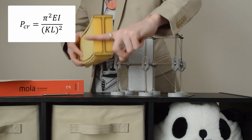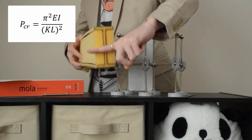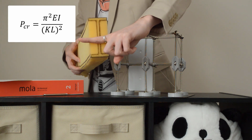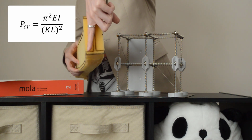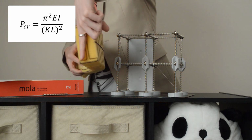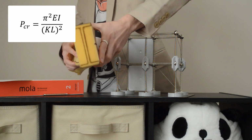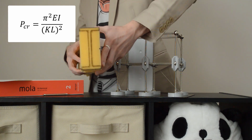So bending about this axis here would generate the largest moment of inertia. And on the other hand, the smallest possible moment of inertia would be calculated about this axis. In other words, I've just identified the strong and the weak axis of this particular shape.